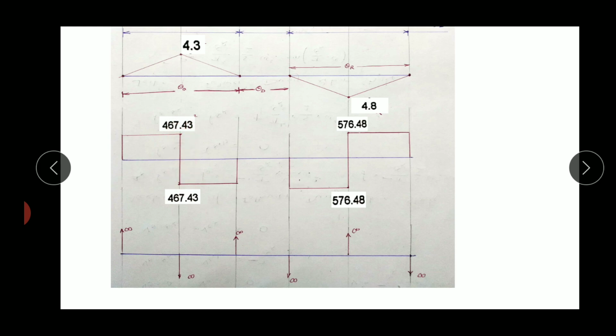As the slope of a vertical line is infinity, an infinite amount of jerk is required at the half of outstroke to achieve a negative constant acceleration from a positive constant acceleration. So an infinite amount of jerk in the downward direction is required at the half of outstroke.